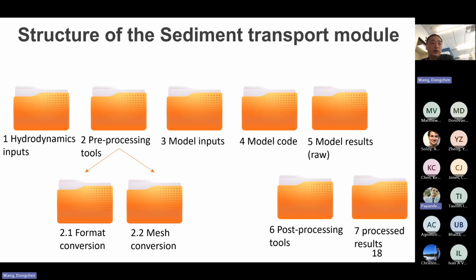The method we are using here is an indirect way. The field team brings equipment called LISST, and they measure the in situ grain size in the river. Then they get a vertical profile of the in situ grain size in the water column.